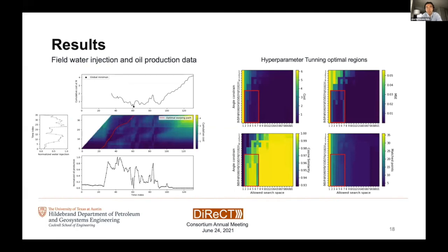Well, that's a very interesting question. I think the gradient of the warping path is going to give us an indication of basically the amplitude. So it's like we're looking at the attenuation effect here, because if we have a larger warping path, that means that our points are more spread on the response signal.